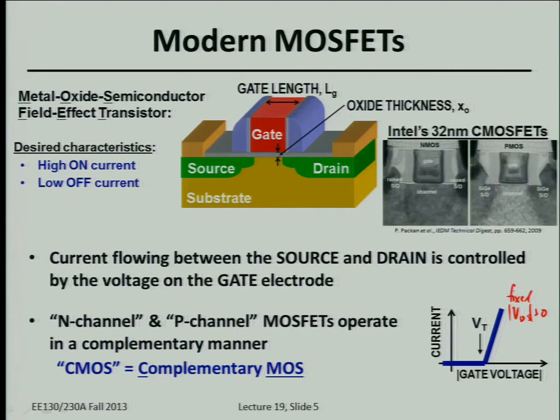And Intel just put into production last year some 3D transistor structures, but until then, the most advanced transistors were still planar. So you have silicon with a planar surface here for N-channel and P-channel designs. And the most advanced transistor designs have metallic gate materials to eliminate the gate depletion effect.